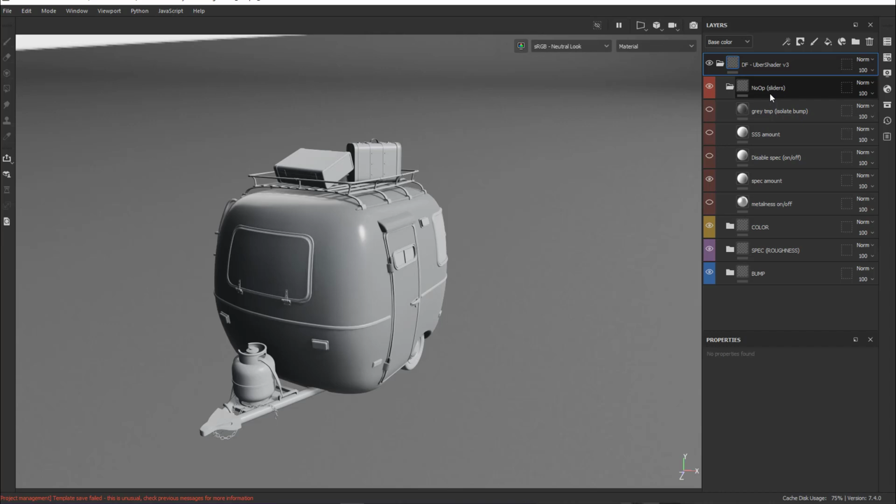So what we want to do is be able to set the shader attributes the same way in Maya and Substance, so our asset will look the same in both programs. This can be done in Substance with fill layers, which retain the values that we set for them. Note that this is not the case for paint layers, which change based on the current brush settings.